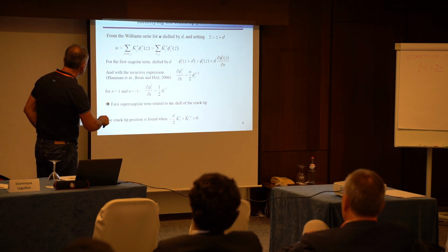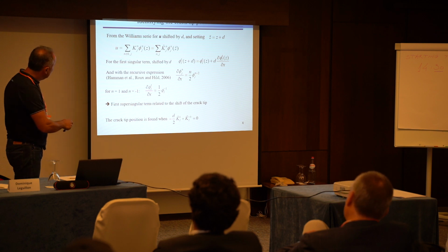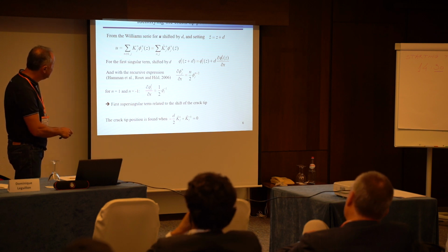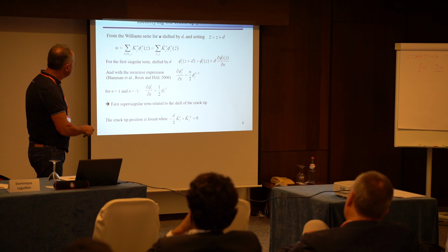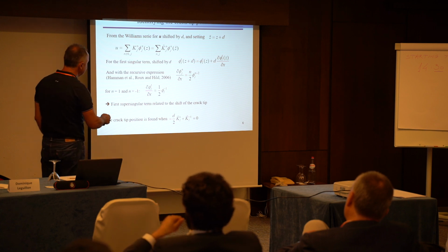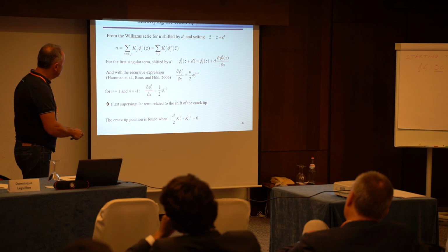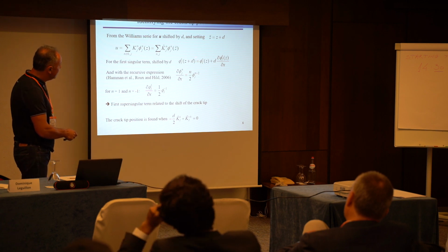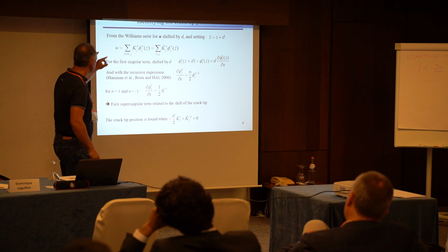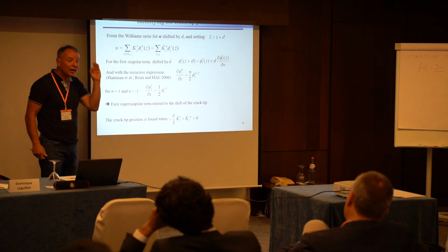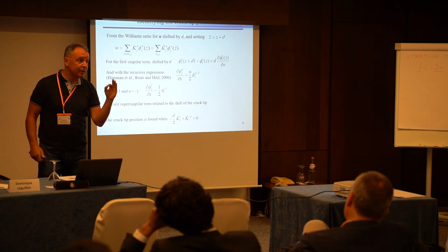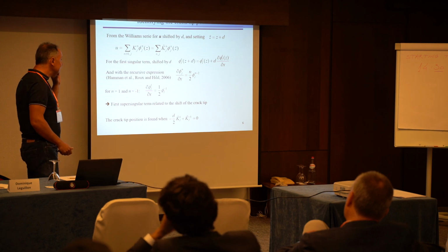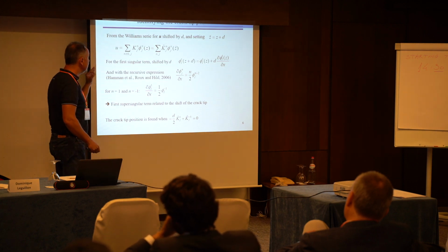So you look for a form of the displacement field that looks like this. That was done already from the late 80s by this community. And people in France around François Hild and Stéphane Roux have observed that to have this displacement field, you have to have clear knowledge of where the crack is. And the crack tip is not easy to identify experimentally.